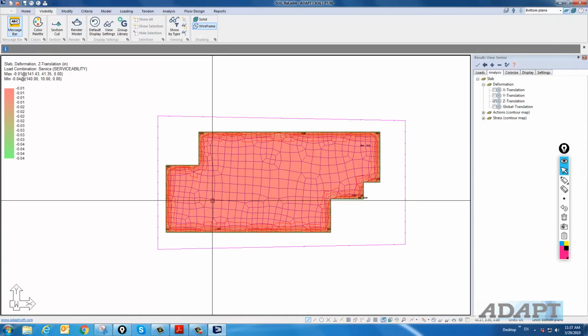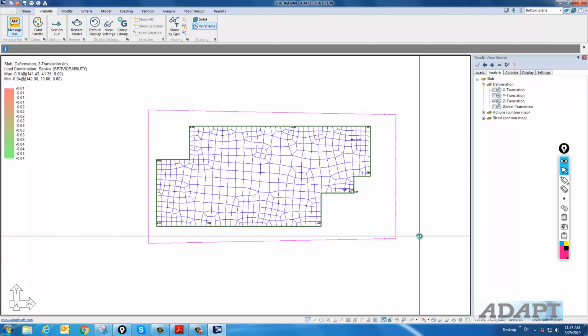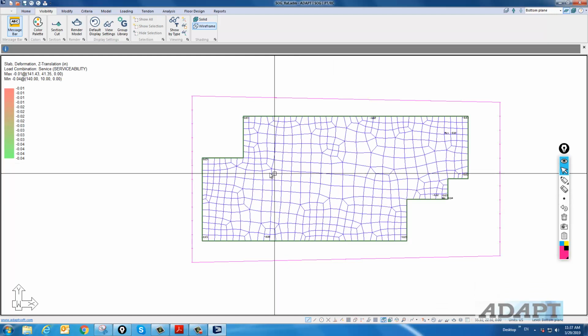spring condition. But what we want to do is set the spring equal to the edge moisture distance. And the edge moisture distance, EM, is typically given by a soils report or just site conditions that have been evaluated. So we're going to make some just arbitrary assignments for EM. I'll go ahead and just close the result display settings now.